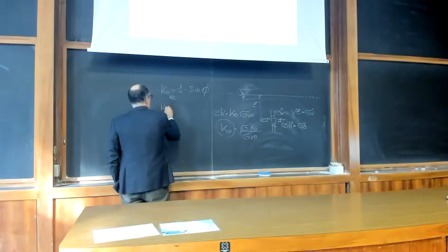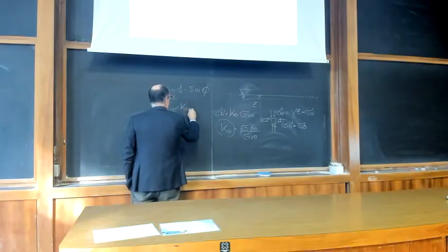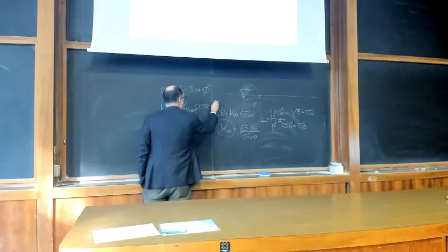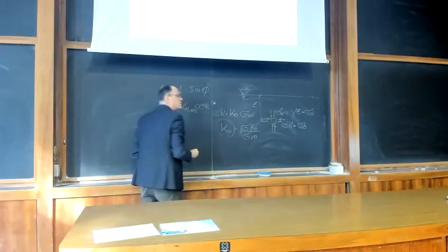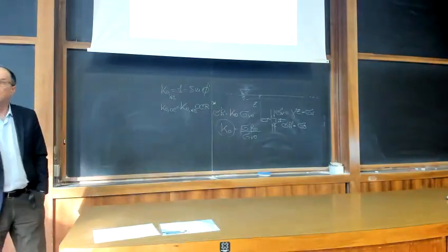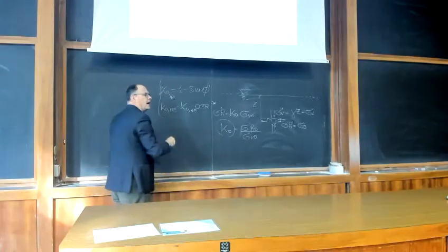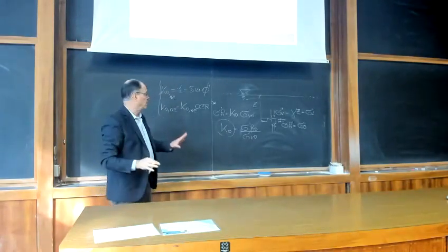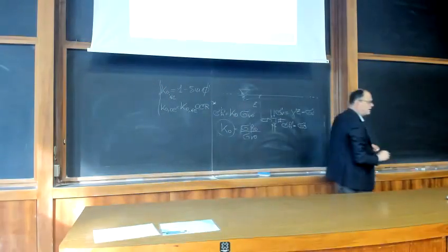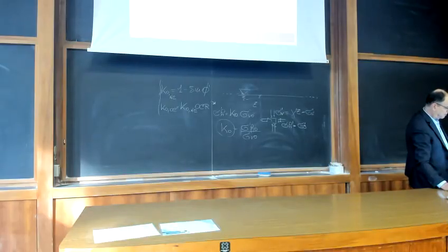For an over-consolidated soil, you have your K0 for the normally consolidated soil times OCR elevated to an exponent alpha, which is typically around 0.45, 0.5, something less than 1. Everything is already seen and I hope well known to you. Why am I reminding this? Because we are in this situation from the stress state point of view.